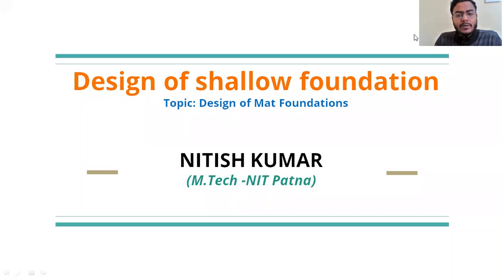So in this lecture, I am going to discuss design of mat foundation. Mat foundation is basically a large slab supporting a number of columns and walls under the entire structure. We go for the design of mat foundation where the soil pressure is low, where the number of columns and walls are close to each other, where individual footings are overlapping with each other. So in all the cases, we can go for the design of mat foundation.